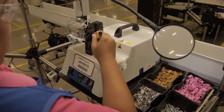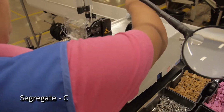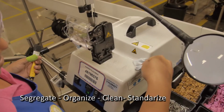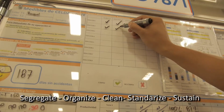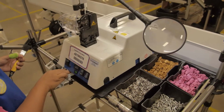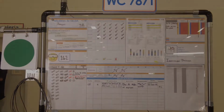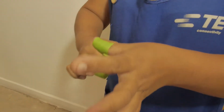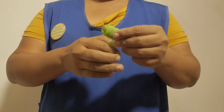As part of startup activities for every shift, autonomous maintenance involves clearing the workstation and ensuring components are in their location, cleaning the equipment, and doing checks to ensure good operation of the equipment. Operator preparation and safety precautions before starting production.